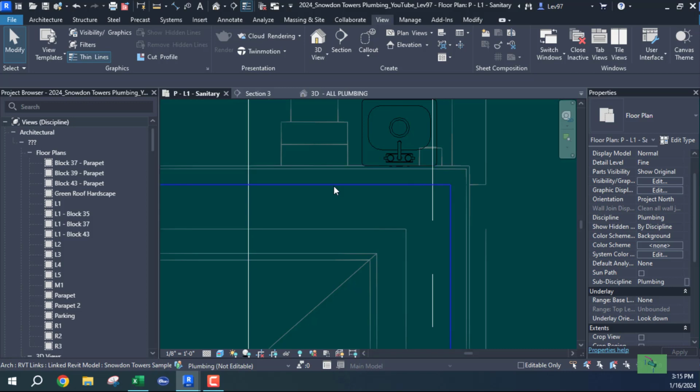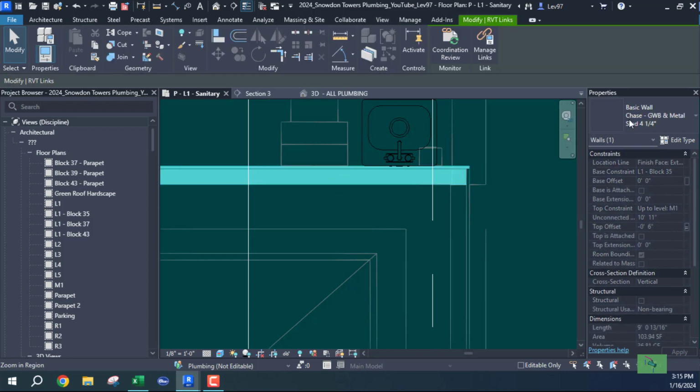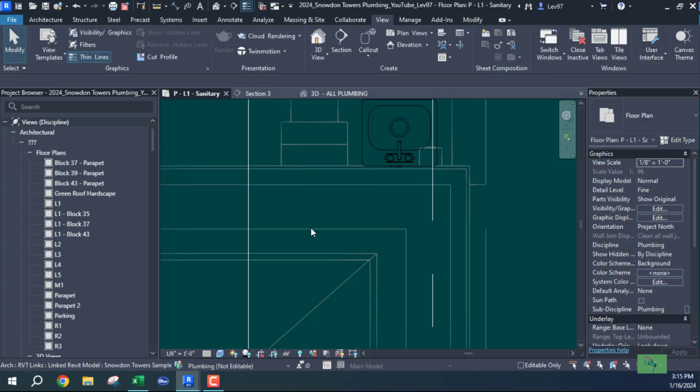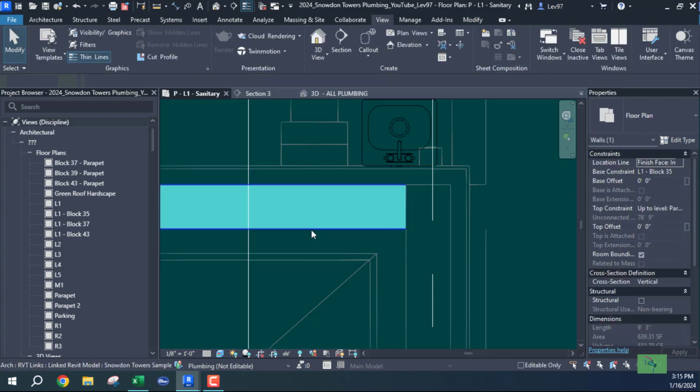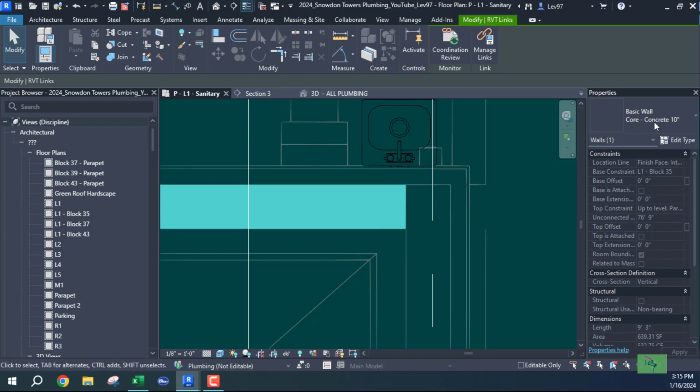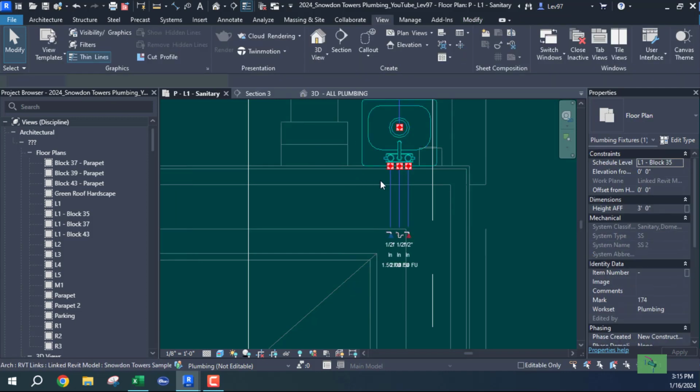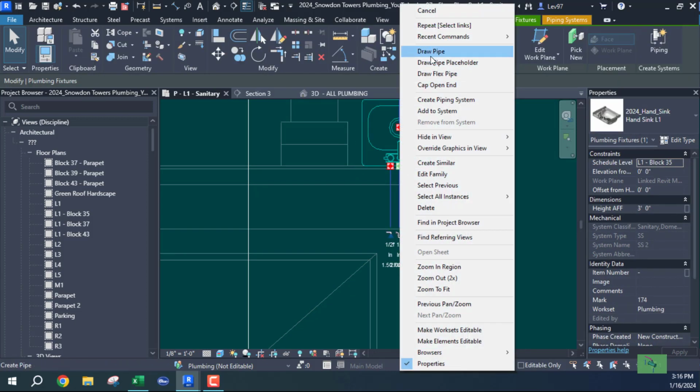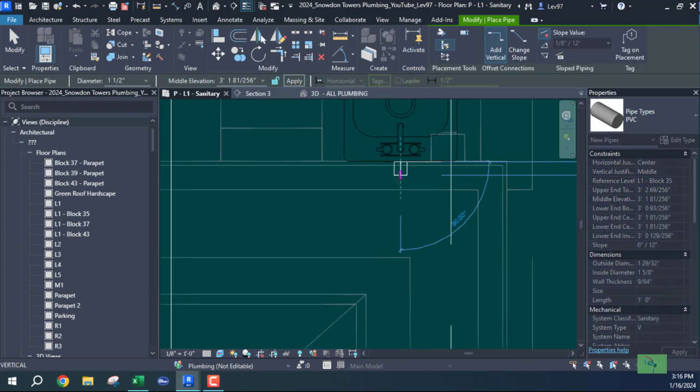Okay, here. That's the stud wall. So I want to stay in my stud wall. I don't want to come out here. This is concrete. All of this is concrete, okay? Which is what is shown here in this properties. So this is a 1.5-inch vent pipe that I want to draw, and I want to keep it in here.